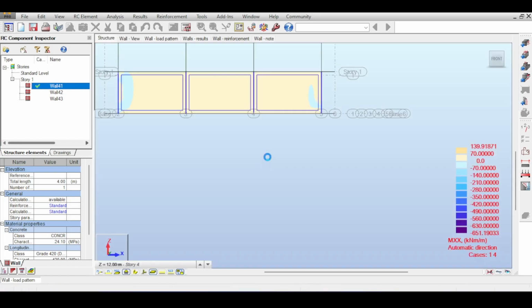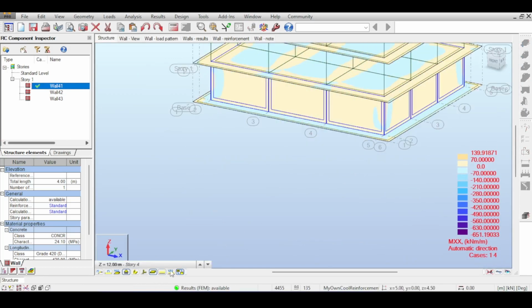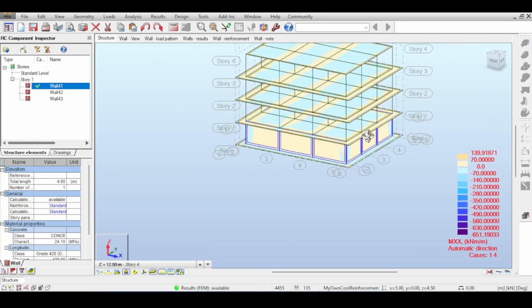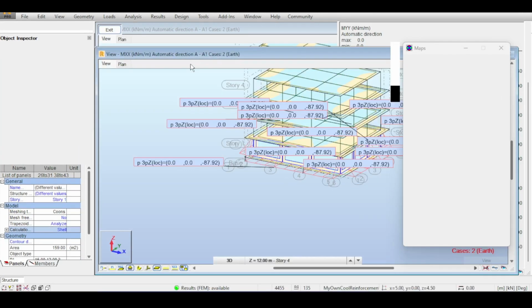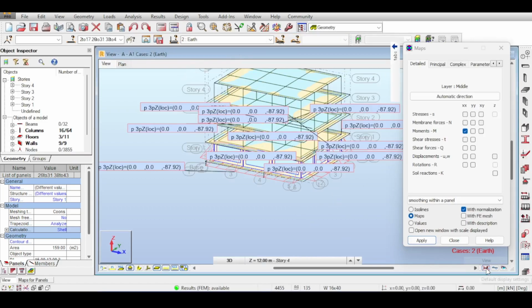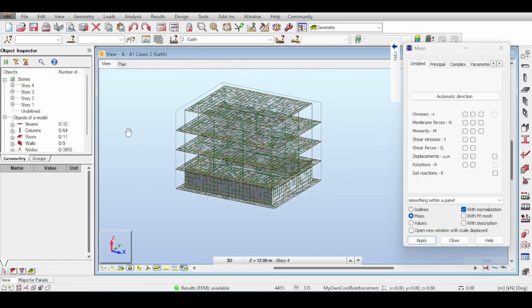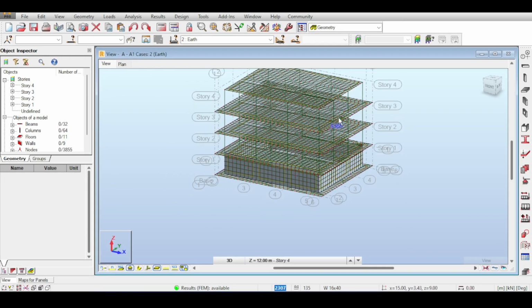In other words, if you have any wall where the load is perpendicular to the surface of the wall, then the wall module is not the module you should go to. This is a no-go at all. You should not even touch that. So I hope that you learn this, because it's very important to understand this. Every time, I see some viewers asking me why I am not using the wall module in my retaining wall before. So that's the answer now.